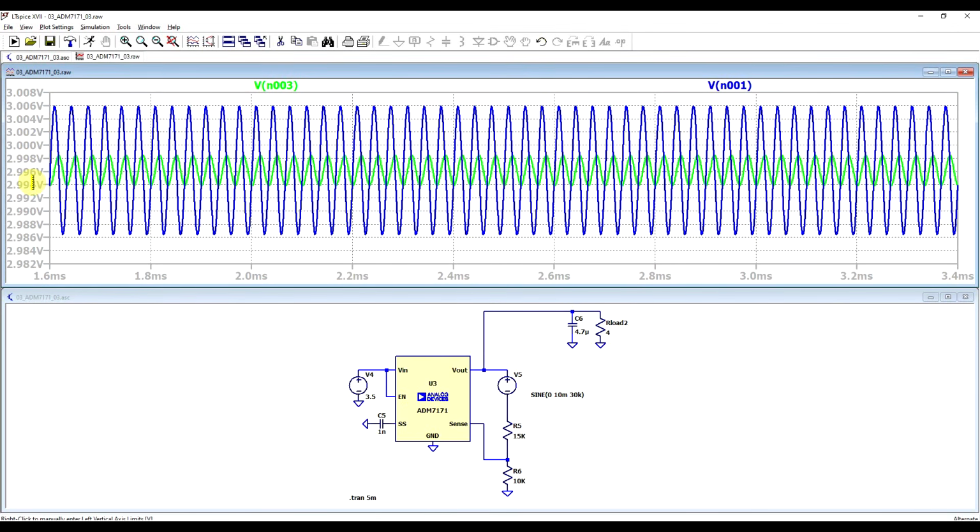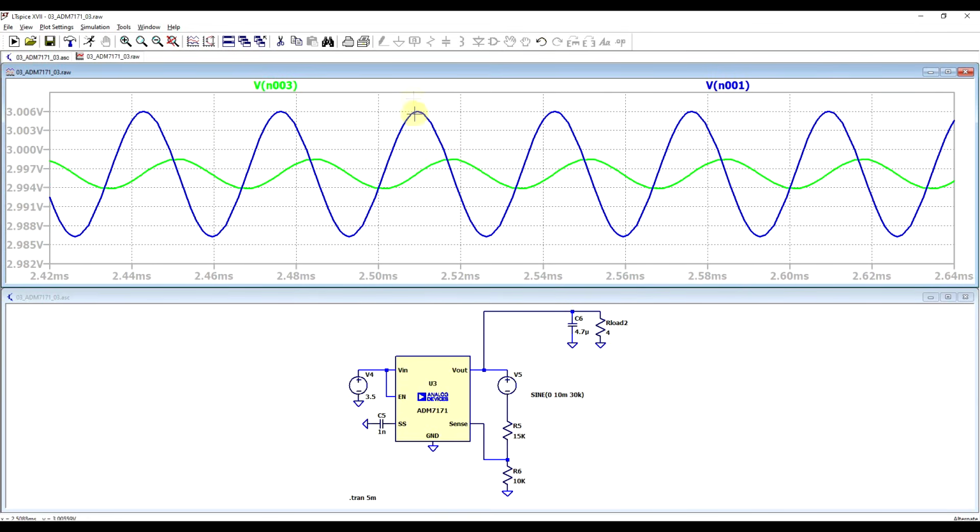DC operating point. Now, by implementing the injection this way, the injected signal and the output result difference will always be more or less under control, since the difference of these points is the exact injected signal. So if we look at the 2 points, so before and after the signal source, we can look at the loop response based on the 2 curves. So the amplitude ratio between the 2 curves will be the magnitude at which the loop amplifies, and based on the timing between the 2 signals, we can determine the phase shift of the loop.